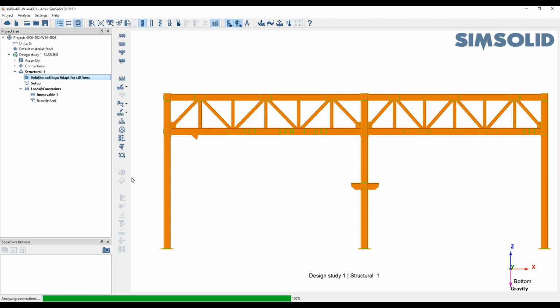Unless you do it as beam analysis, but beam analysis is very quick, but then again, you don't have the ability to do the bolted connections, because with beam analysis, we have to assume that everything is connected. And what typically happens in the FEA or structural world is that they'll do a beam analysis of this frame you see on the screen, and then they do a localized study, a bit like what we did last week with bolted connections and fasteners. That's one way of doing it, and that's a valid workflow.